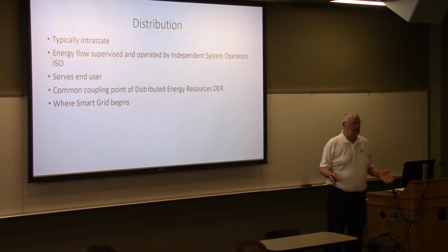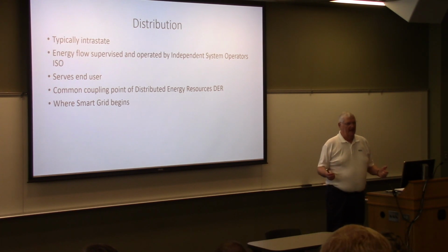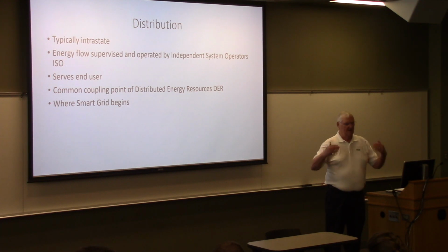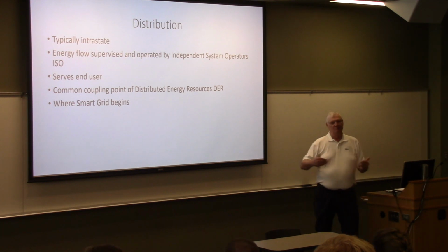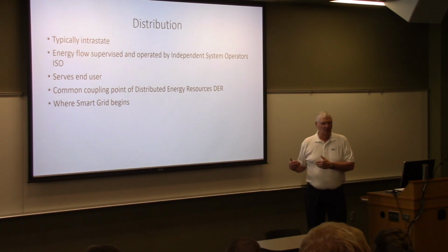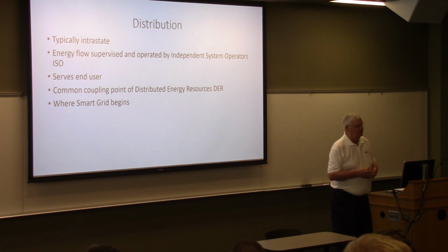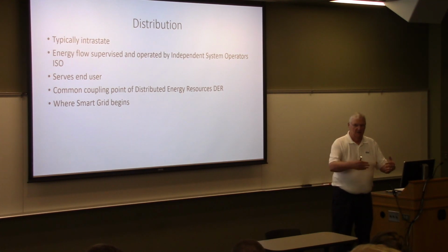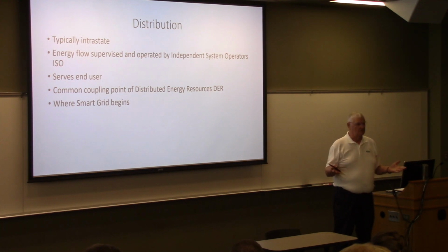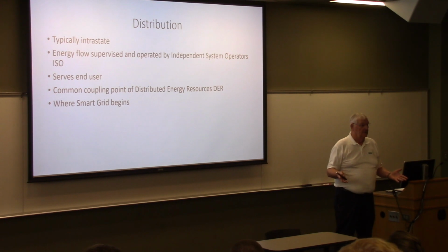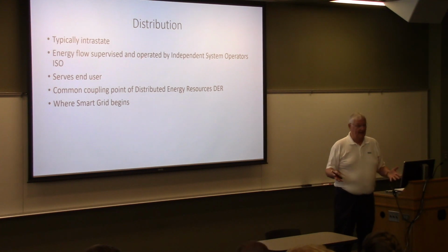Smart meter or smart grid is that up until now, all of your energy is measured at the generator and at the substation. But all of your use is below the substation. So what the smart meter does is it enables you to find out where the energy is being used below the substation. And when you run into difficulties in various areas, because over half the outages and faults that occur on the distribution system, it enables you to determine immediately where the outage is, because the meter that's without power calls and says, hey, I'm without power.